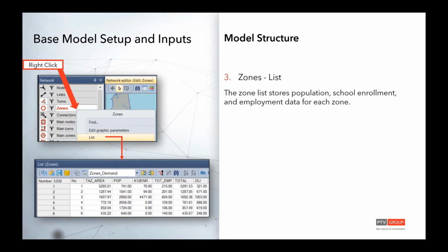But if a zone ID, for example, is changing its TAZ number, we have a specific attribute called TAZ area, and there's another attribute for TAZ number, and you can go and just change that value. So that within Visum, the structural ID stays the same, but maybe you split it up. And you can have an attribute that says old TAZ number, right? And you can do lookup tables and things like that. So using user-defined attributes, you can keep the data even though some of the IDs might change, but still be able to compare the two as long as the actual numbers themselves don't change.